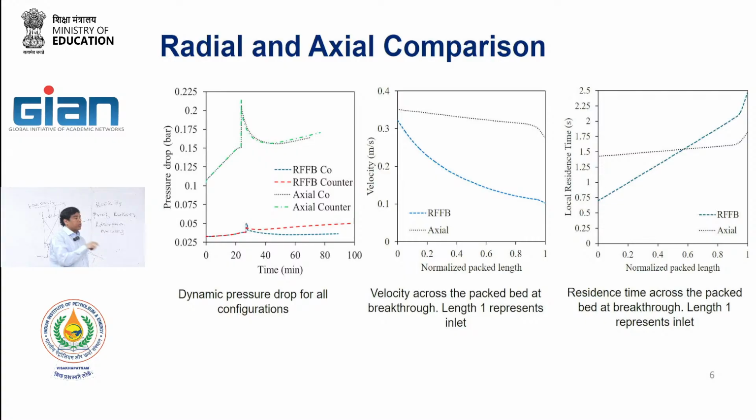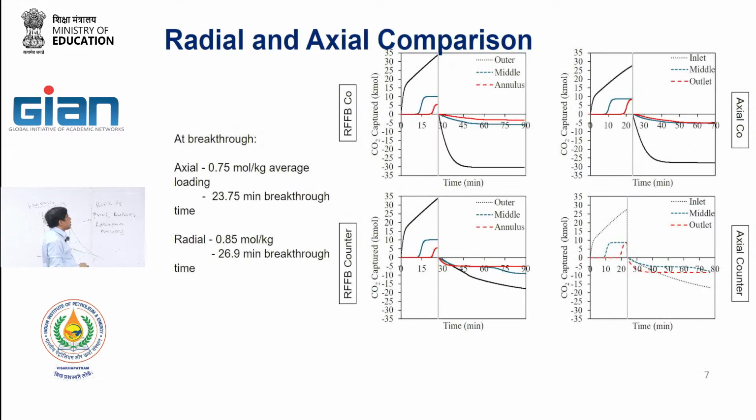Now, the thing which I always keep saying is that this is all what we did for a commercial scale design. Notice the residence time, this is in seconds. In a commercial scale reactor, in any typical industry, petroleum, petrochemicals, cryogenic and so on, the residence time can be seconds, milliseconds, 2 seconds, 1 second, 3 seconds. That basically means your kinetics has to be very fast. Without that, you are saying I need an ocean of solids if my kinetics is very slow. So that is what it shows you.